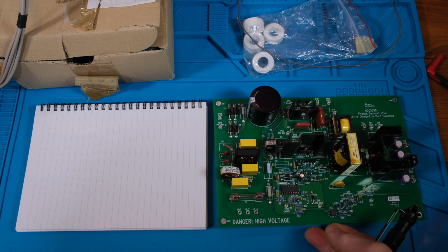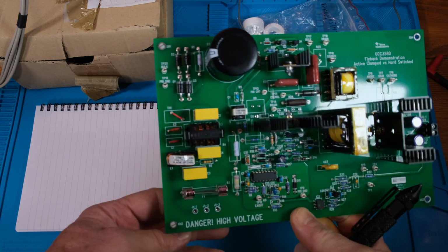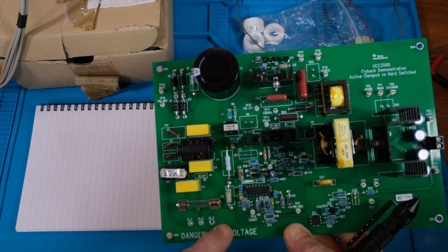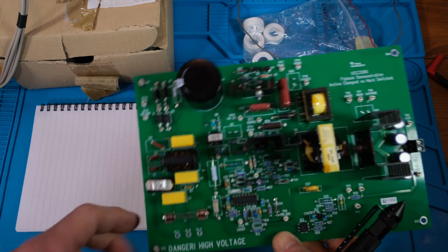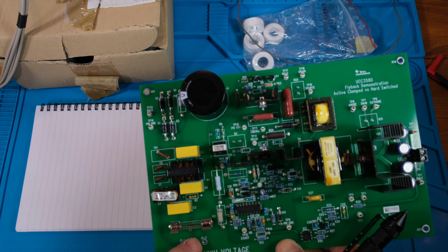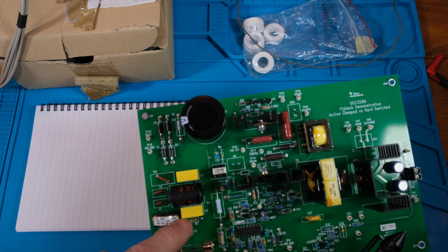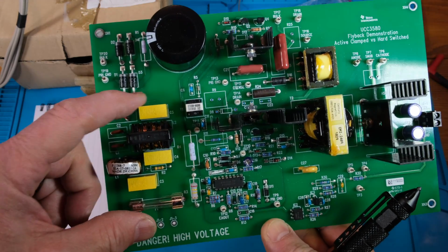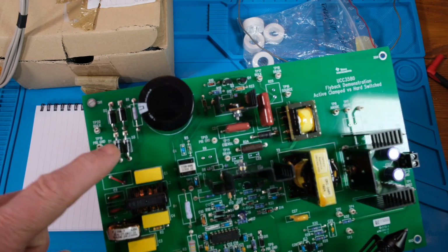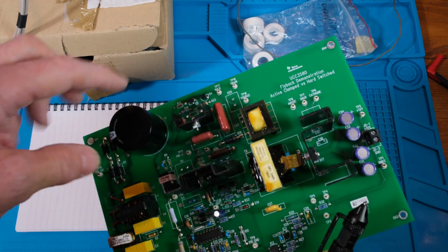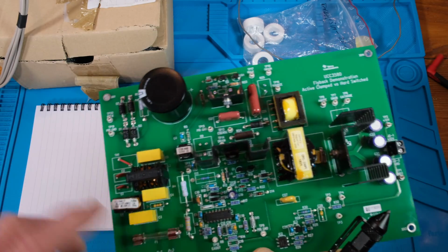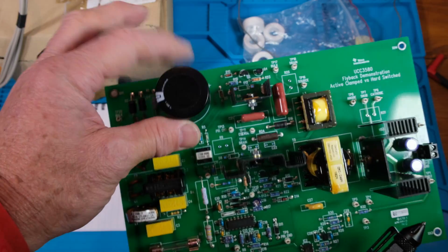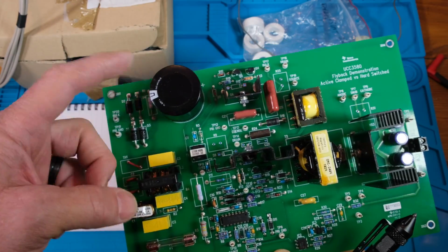Alright guys, so this is a power supply we're going to look at. And this is the input terminals right here. Danger, high voltage. So your input voltage comes in here, and of course that's an EMI filter. And once you've seen them, you start to recognize them. And then our bridge rectifier, our bulk capacitor, and then the rest of the power supply. So this is the input circuit to give our bulk voltage right here, our DC voltage right here.